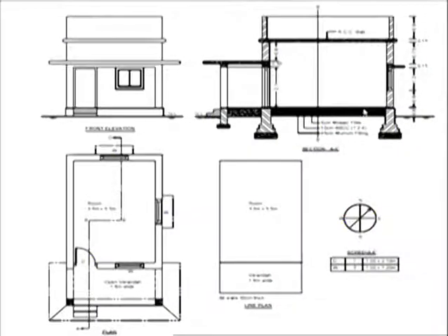So depending upon the size, it varies from 2.5 centimeter to 3 centimeter, and beneath that layer of the tiles, a thin layer of the mortar is laid. That thin layer of mortar may vary from 2 centimeter to 3 centimeter thickness, and beneath that a concrete layer, lean concrete, is laid. Lean concrete means having less cement content. Beneath that the soil filling is there.